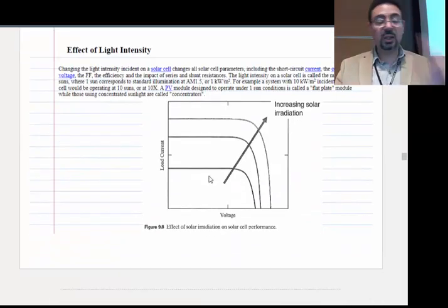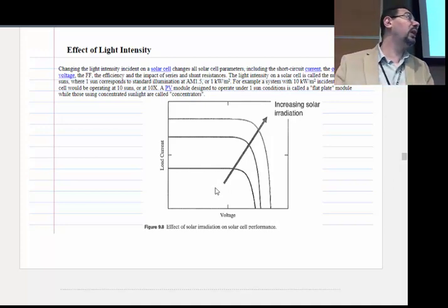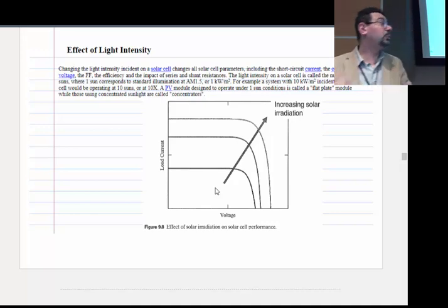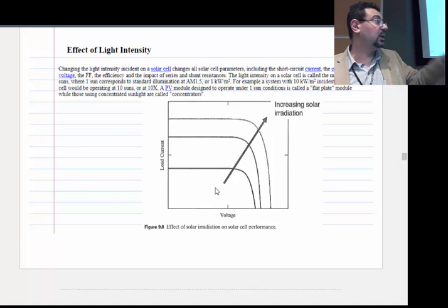Right? And we finished last week by saying that you need to note that as you send more and more photons, you will get more and more electrons. So chances are the output power from the photocell or from the whole PV panel is going to be proportional to the incident radiation. So if you get a sticker on the PV panel saying 300 watt, that 300 watt will go up and down depending on, are you sending one sun on me or less?